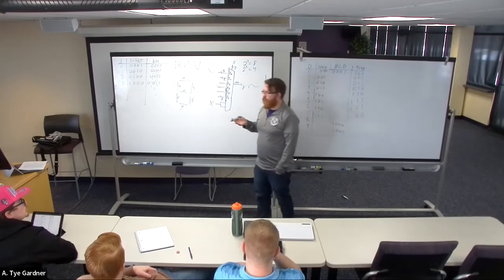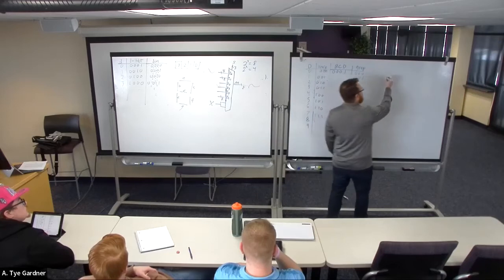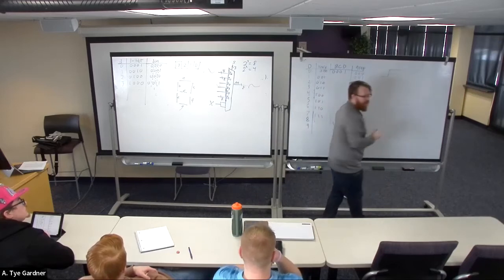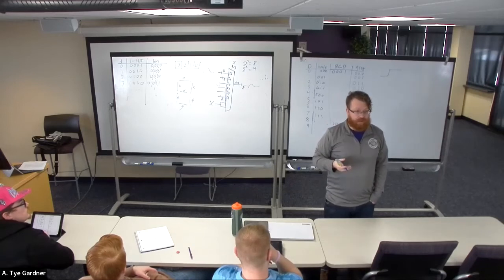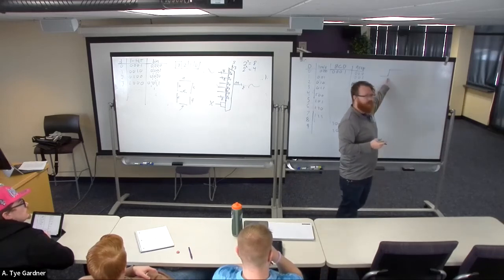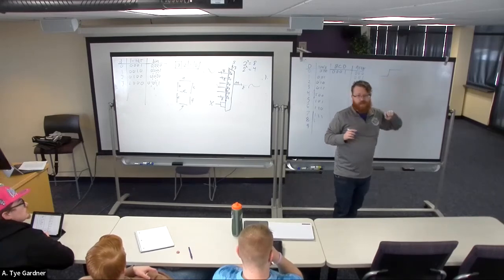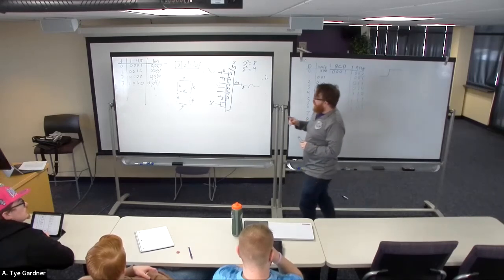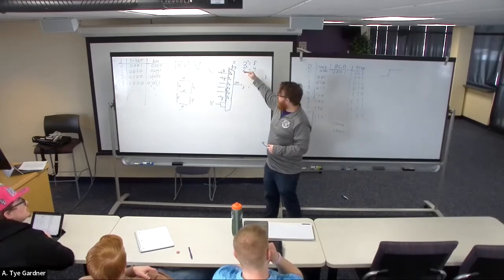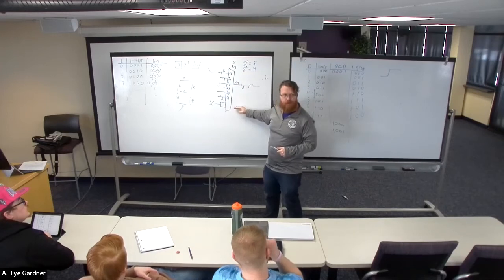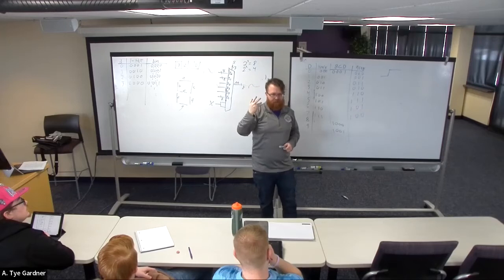Well, there's an issue: digital signals step, right? They draw a lot of current during this change. So we get this really high spiking transient current. When I did the initial design, if this was 0 0 0 and this was 1 1 1, when I would step through all those channels and get to 1 1 1 and switch back around, every single one would flip.